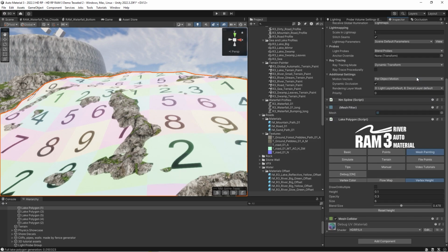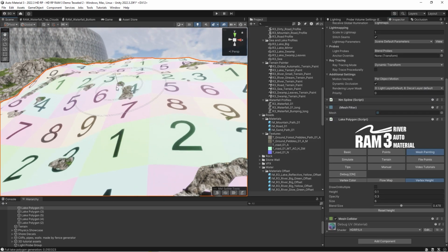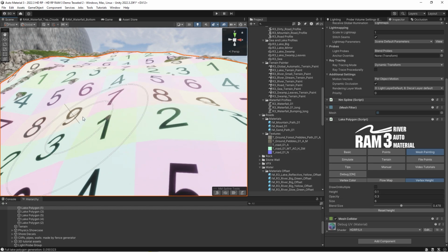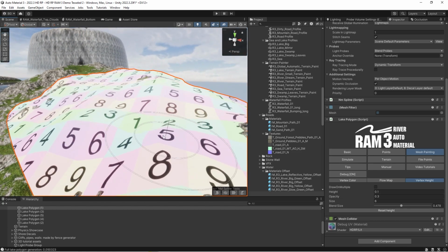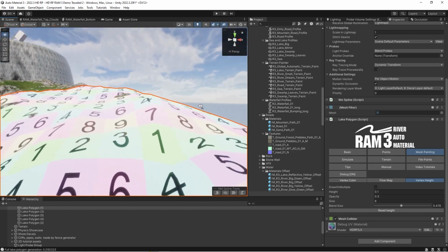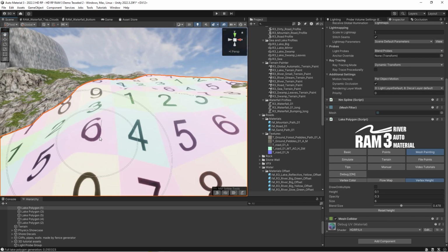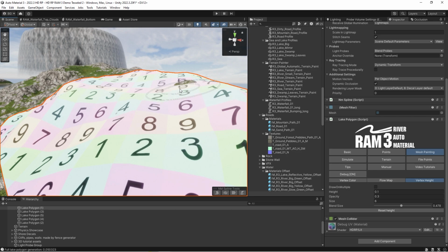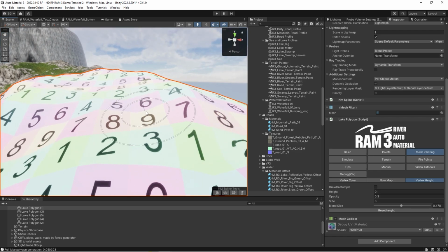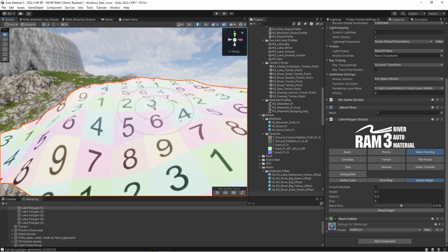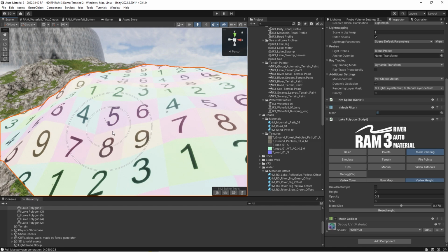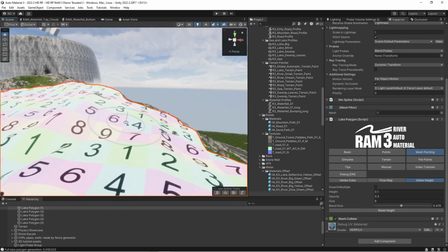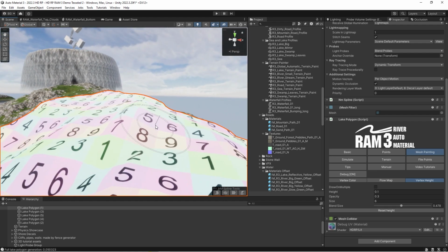You could always use mesh painting, vertex height, and simply cover and move up or down the shape of the lake. So you could simply paint the height of the lake surface. It's pretty useful. First of all, you could keep a low resolution of the lake, cover the whole terrain, and fix it by painting.